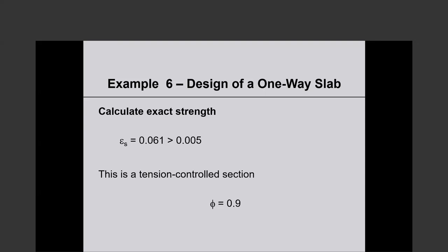Okay, go ahead. Yeah, I'm just trying to rephrase the question. So, if on one side of a beam there is a column and on the other side there is a shear wall, what should be the span? So the beam is bearing on a shear wall. That's fine. If the beam is bearing on a shear wall, it is no different from a beam bearing on a column. I don't know. Because the shear wall is stiff, you think the span should be changed.